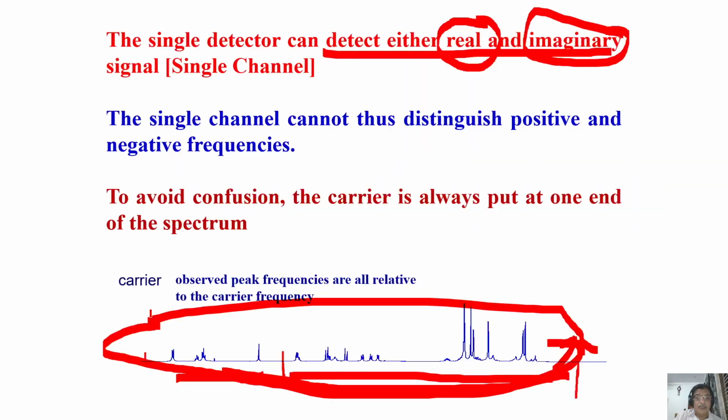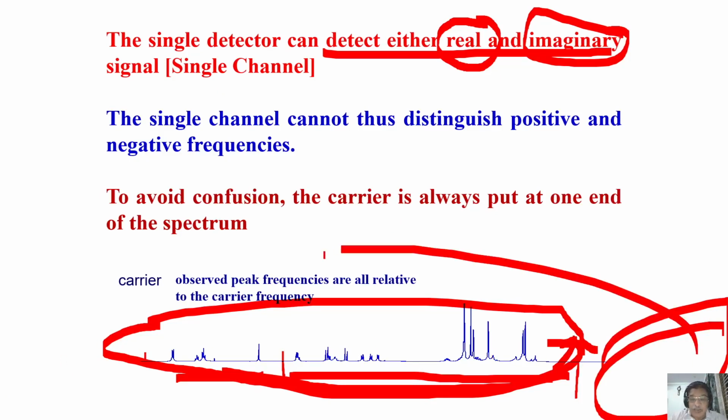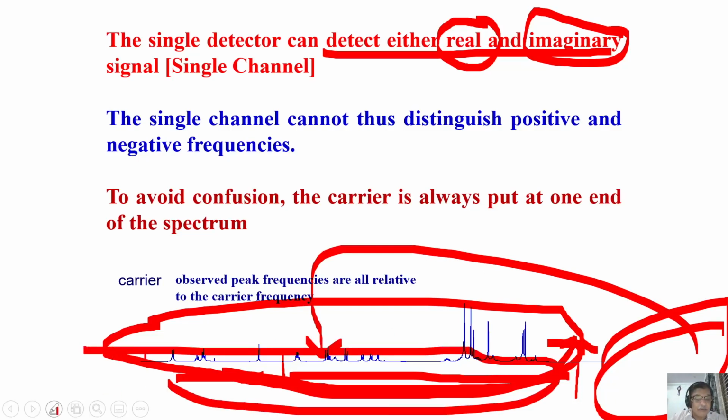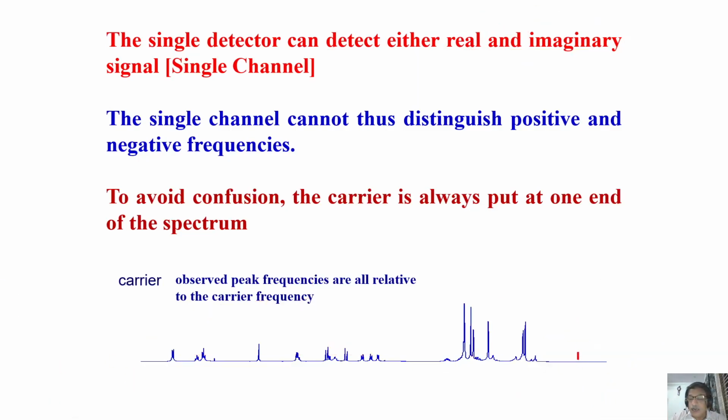For example, if I put my receiver here, remember my Nyquist frequency? There are certain frequencies on this side. It may be noise. Noise has higher frequency than this. This is my region of interest. This noise will fold back here. Is it not? Noise beyond this carrier offset has to fold back into the spectrum. So the noise level will be there.